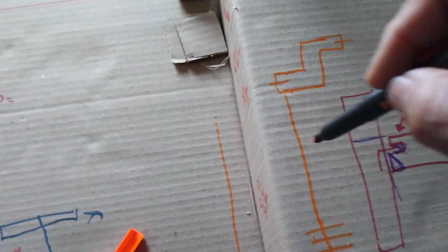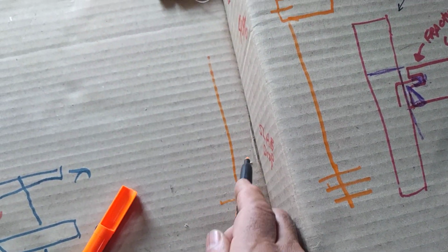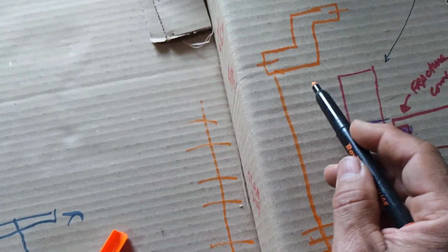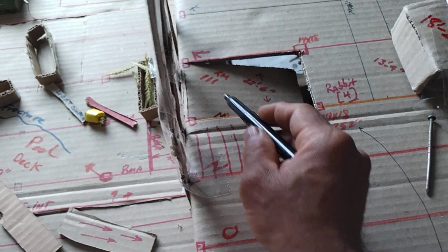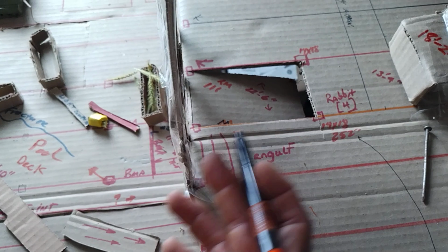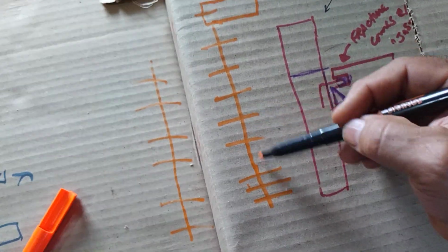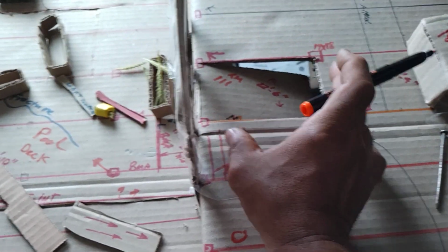So it's possible that is what we're looking at here. So there will be rebar in here, right? So rebar, and then rebar here tying into this slab. If that's the case, we can get a tug. It separates from this rebar here, from this slab here, and it drops this section down.